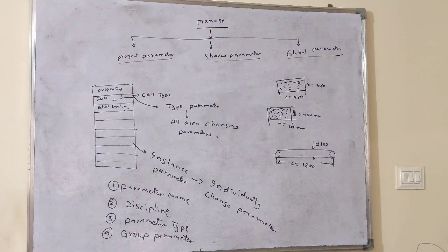There are two types of parameters. Now if you change something here, this is the A grid, and I am changing something on this A grid. Before, the scope box here is none. If I put something here, it will be affected. Here the type is by type, but I am changing this grid to yes.